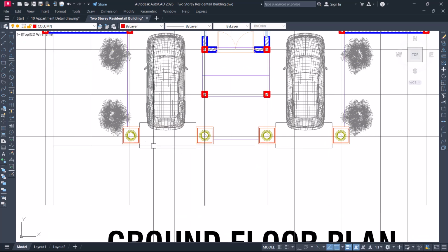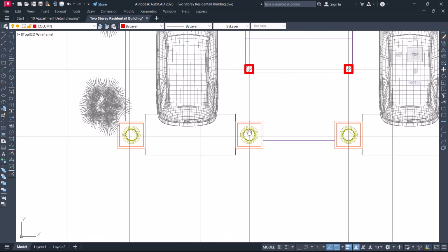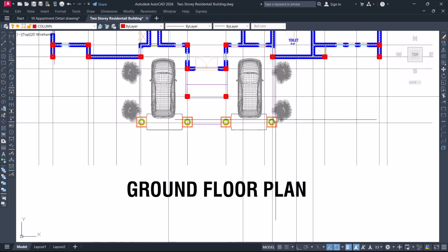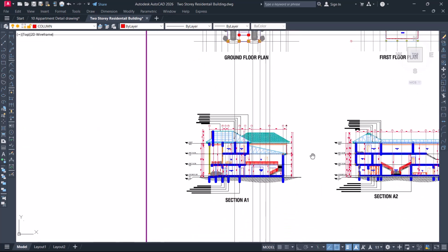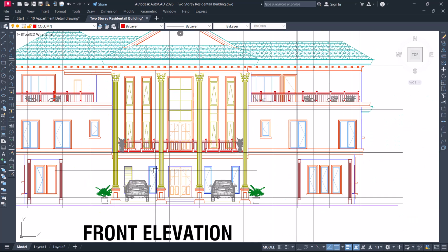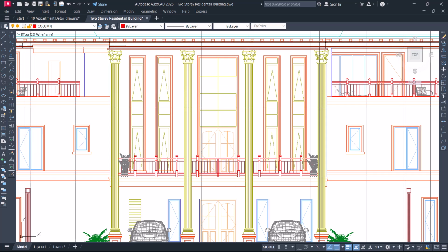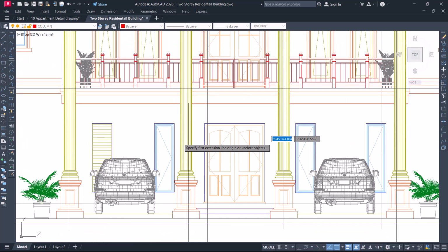If you look, we have circular columns, right? Circular columns are at the front of the building, which is the entrance, and you can see the columns here. So we need to also model that column as a circular column, using the column layer to model it. Else it will not show on the software. Now before we put that, let's look at the diameter of this column.